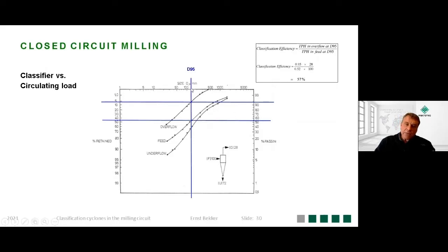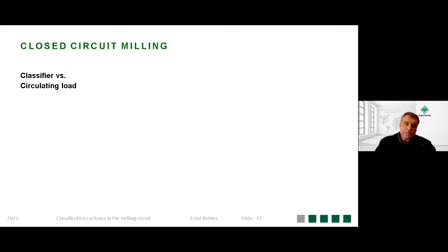That same size fraction, extrapolate it to the feed section. Look at the percent passing in the feed, and you know what tons is going into the feed. And by then doing a mass calculation, we can get to the classification efficiency. So for the sake of this discussion, in terms of classification efficiency, that is the formula that has been used, and that is a general formula used in the industry. Again, do not confuse it with the separation or the Tromp curve. That's just another mechanism by which we as suppliers evaluate the efficiency of a hydrocyclone.